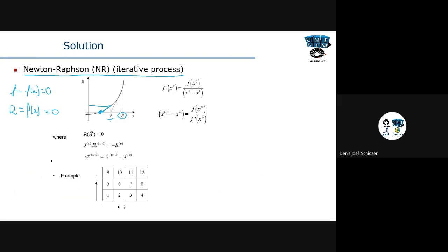And that's why the simulator keeps doing different iterative procedures, where in the beginning we're going to guess all the oil pressures and water saturations and gas saturations for all the grid blocks. We're going to check all the residuals, and for all the residuals, we're going to check if they are 0. If they are not 0, we're going to use these Newton-Raphson equations. And we're going to get at the end of the process the P_o at n+1, and the same for the saturations at n+1.